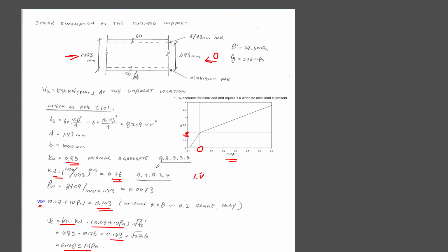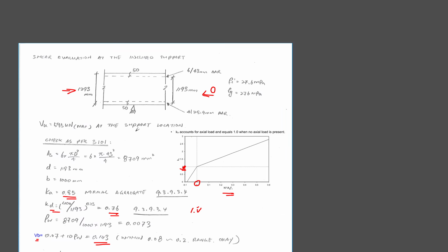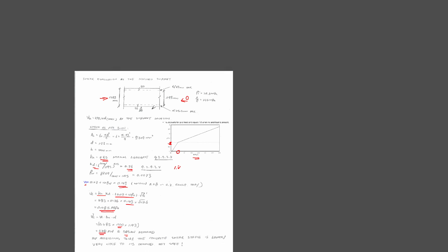If you test a small beam, like a 200, 300 small beam, the deep beam has never been tested. If you adopt empirical formulas derived from small sections and use that formula to design your deeper section, that's where things don't line up. So that can probably explain a bit why old structures tend to fail in shear in this case.